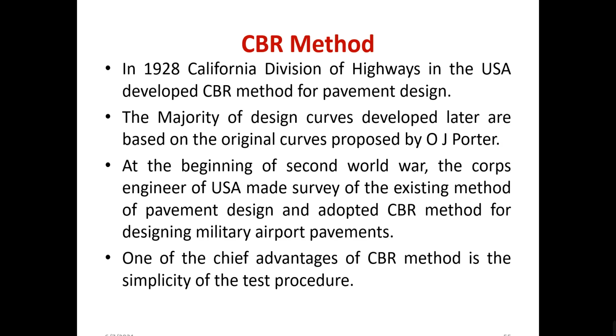So the CBR method of pavement design is very important for designing the thickness of the flexible pavement. First of all, you need to understand what CBR means: California Bearing Ratio Test. For any soil upon which the pavement has to be built to perform well, the soil should have stability. Stability in the sense that whatever penetration is made upon it, the soil should have resistance to the penetration.